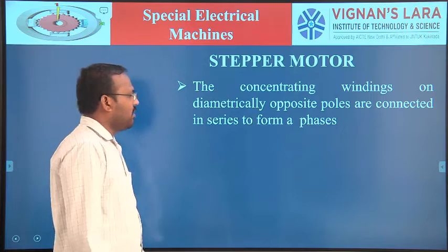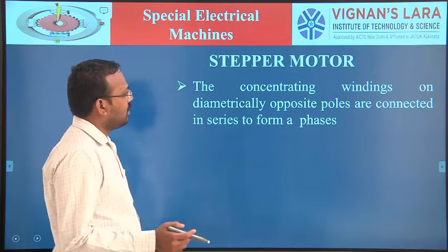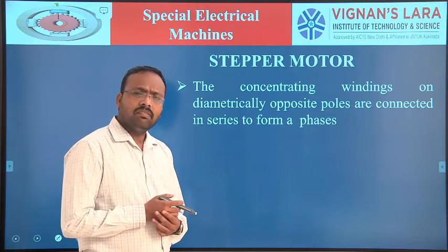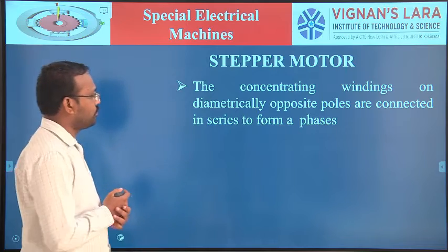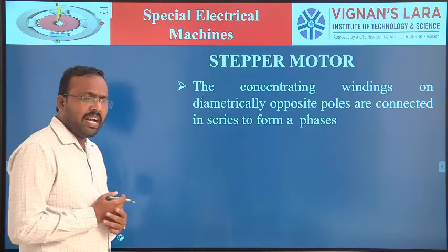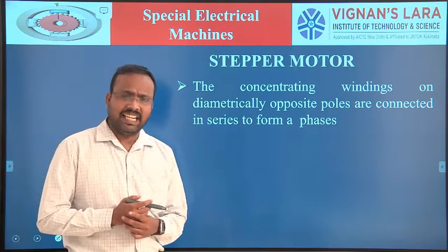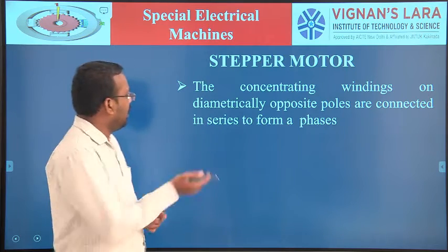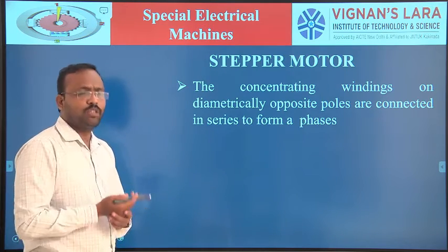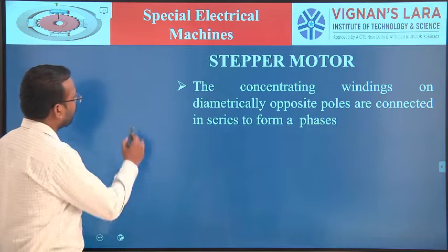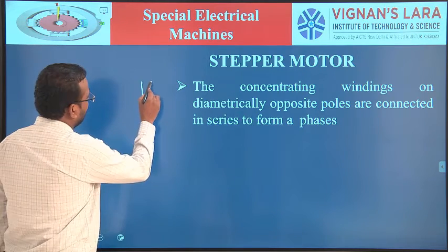The stepper motor has concentric winding on the stator poles. These windings are connected in series on diametrically opposite poles. See here, this is your stator.